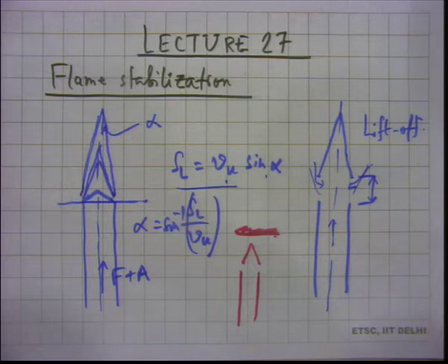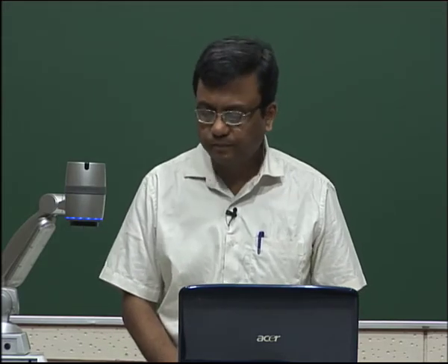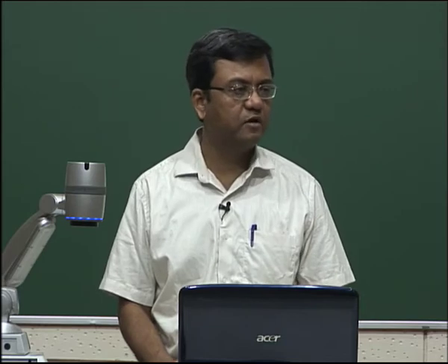So, lifted flames are typically not desirable. If you are a combustion engineer and you are trying to use flames to heat something, then you will not like to have a lifted flame. By design, we are not trying to get a lifted flame. If it happens, then it is better to change the burner design, change something, change the flow, and make sure that the flame gets anchored back again to the burner. So, the lift off situation is undesirable.